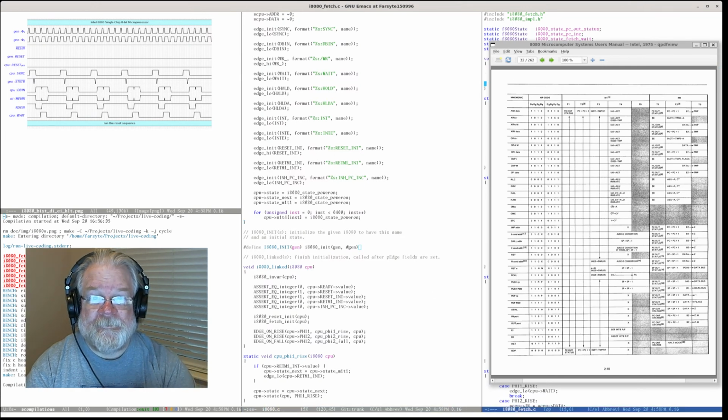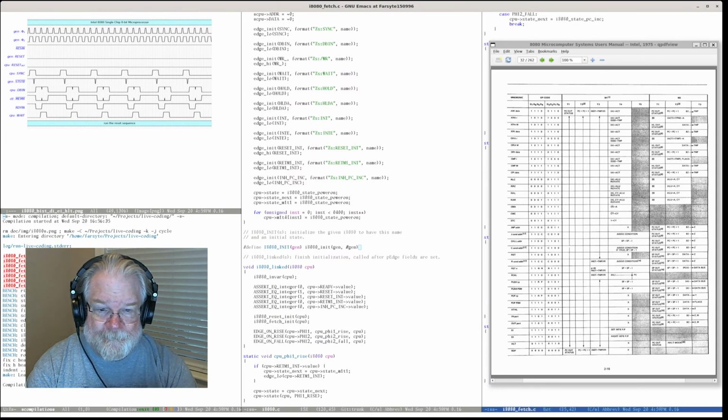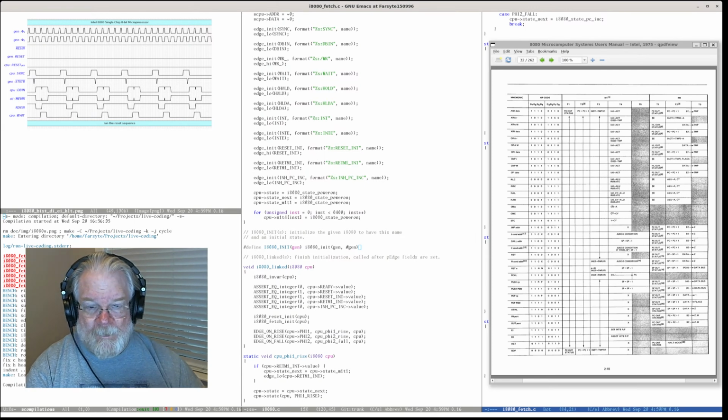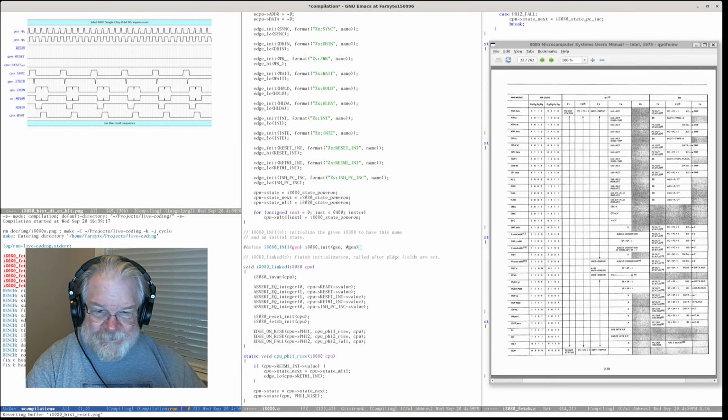And now, where we diverted to state X, we now do the decode. We have now implemented instruction decode in the most general way possible, trading all the space we need for all the time possible.